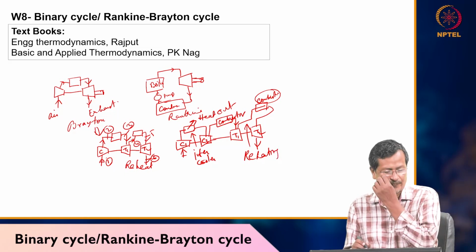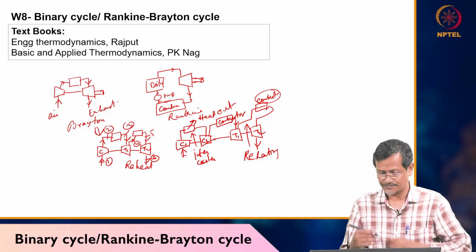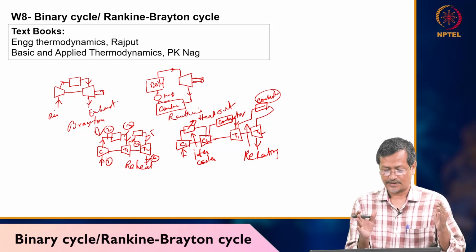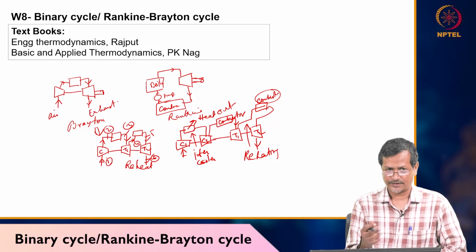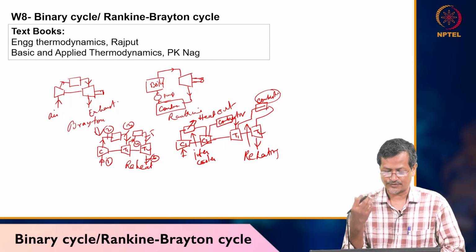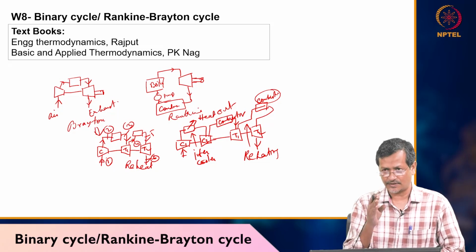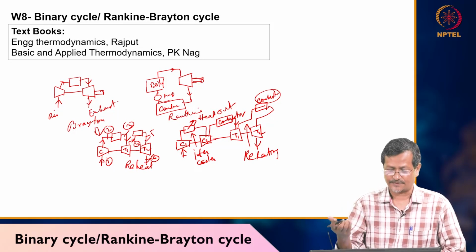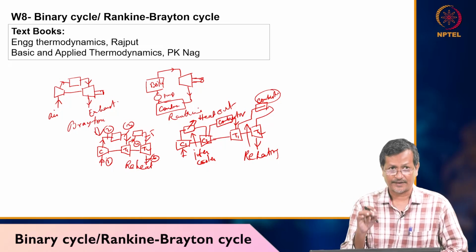In previous lectures, for example in the pump section or turbine section, we discussed that a single-stage compressor takes more energy to compress the same amount of air. But if you have an intercooler, then compressor performance increases. That's why we use intercooling, or we remove some heat between every stage of the compressor system. In the turbine, we can again increase performance if we reheat the system. So one turbine system can have multiple intercoolers and multiple reheating stages.